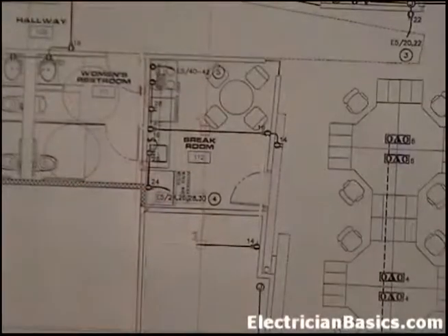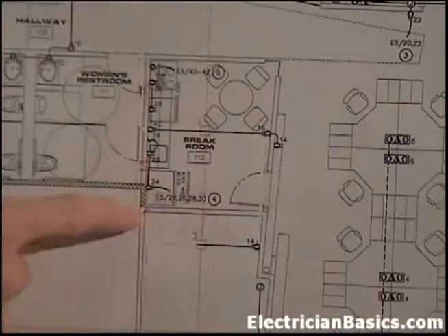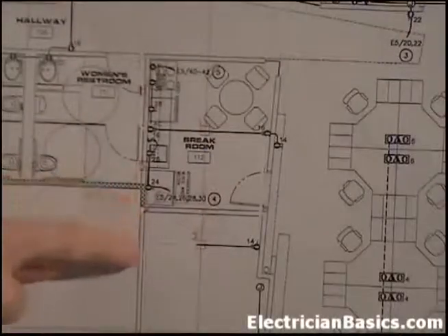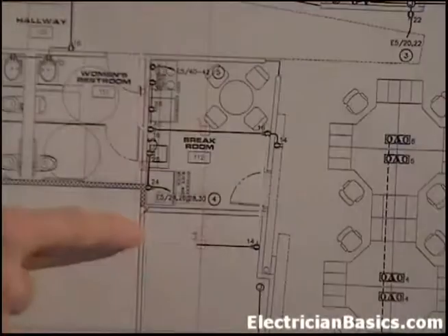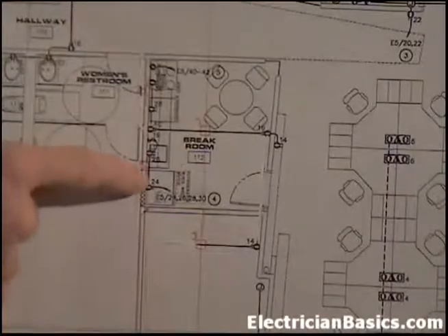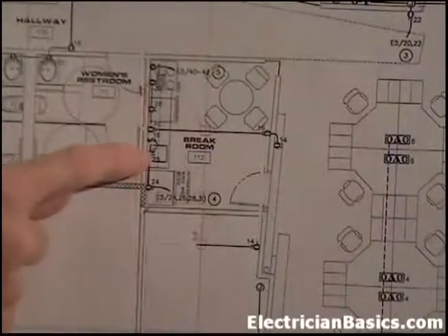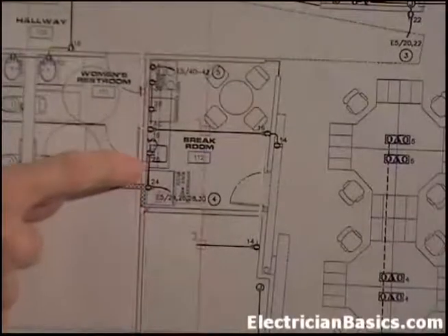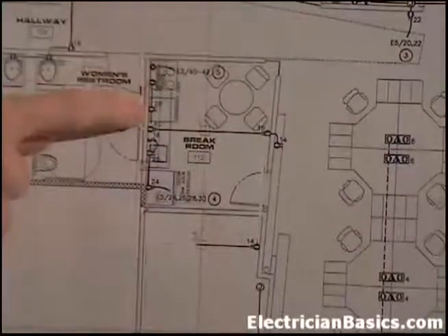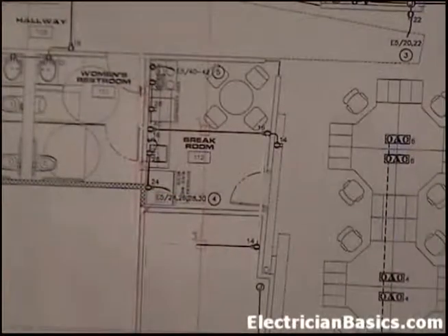It's pretty straightforward. What we've done, I've just made a red line circle, pointed over here, and remember that note 2, we had a unistrut on the wall. So what we did, we ran the unistrut on the wall, then a conduit on the unistrut, and we just dropped a J box here for these circuits, and then from the junction box we went here, made another J box for 28 and 30. So we got 24, 26, 28, and 30 in the same J box.